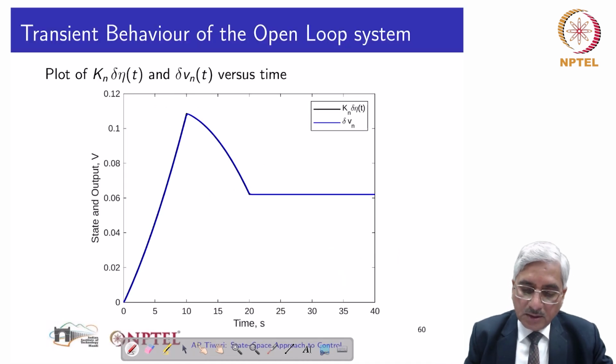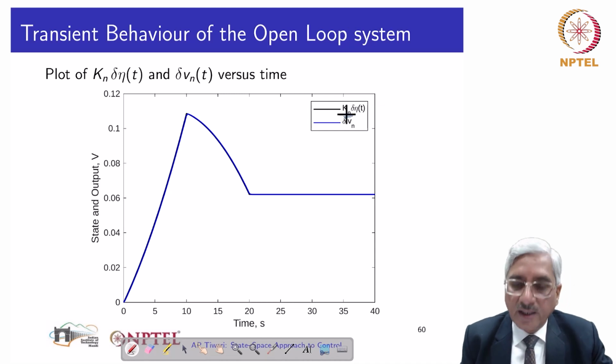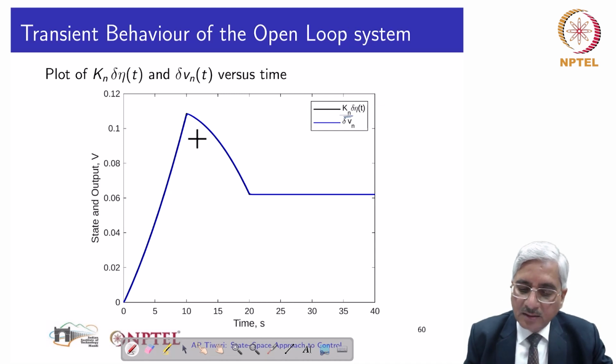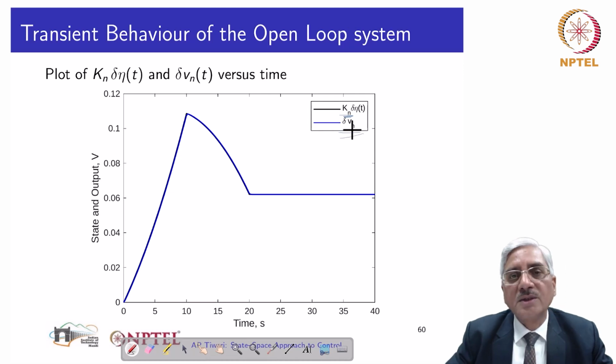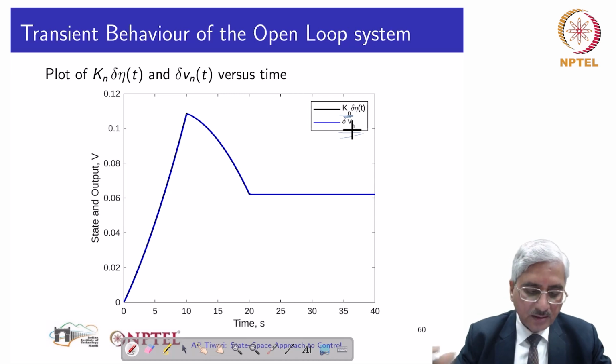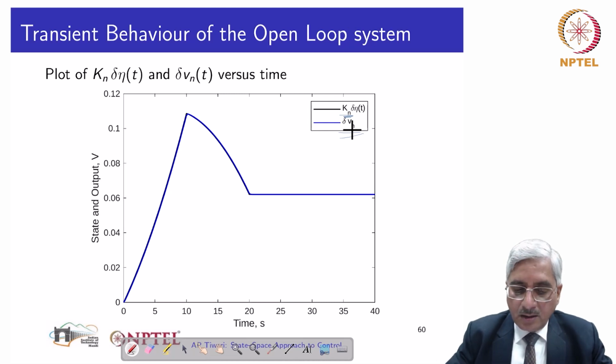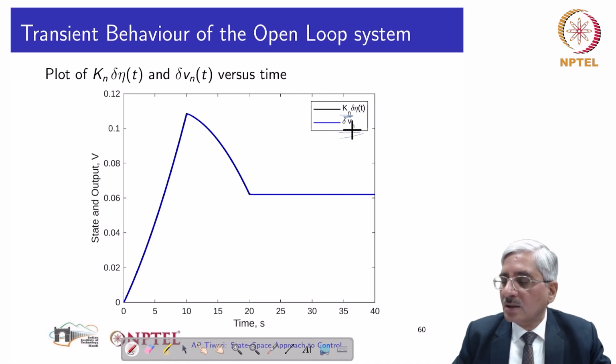Now the reactor power multiplied by that sensitivity Kn will vary like this, and also the output of the amplifier, which is measuring the neutron density, will vary like this. Neutron density and reactor power are proportional quantities, so I'll end up calling it reactor power in place of neutron density. You should also understand that both are synonymous quantities related through only a scaling factor.